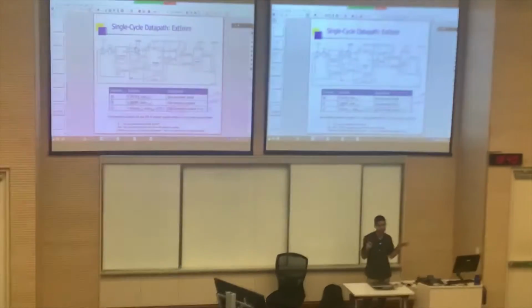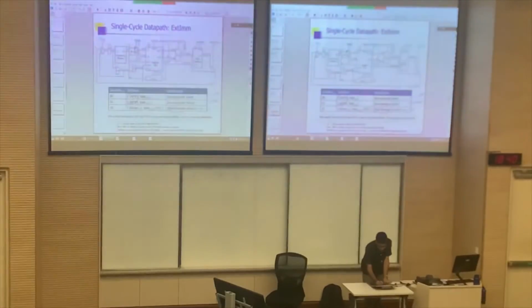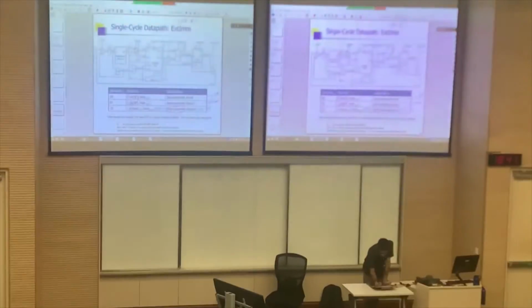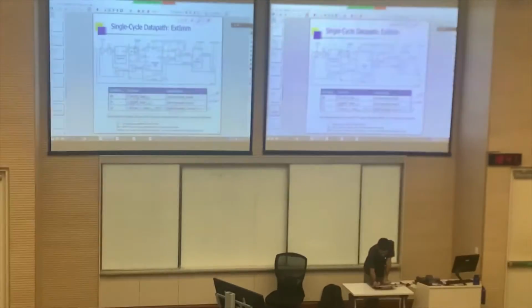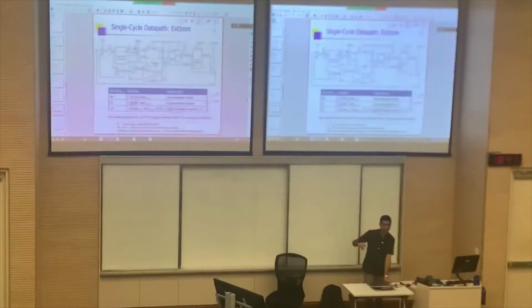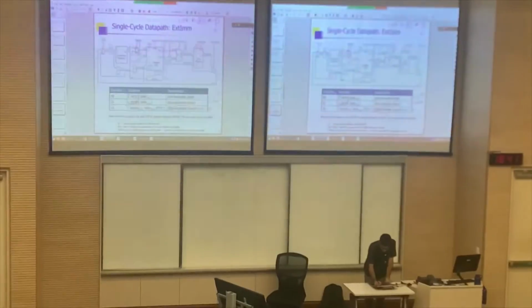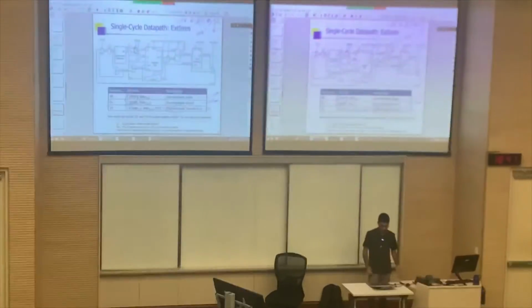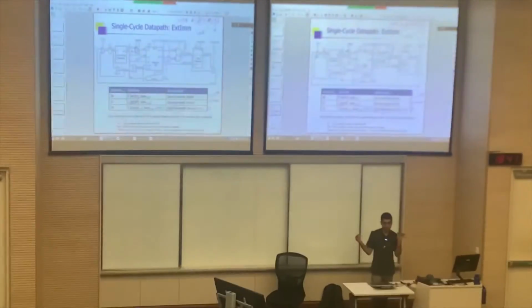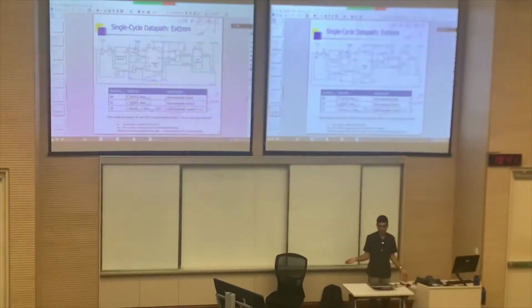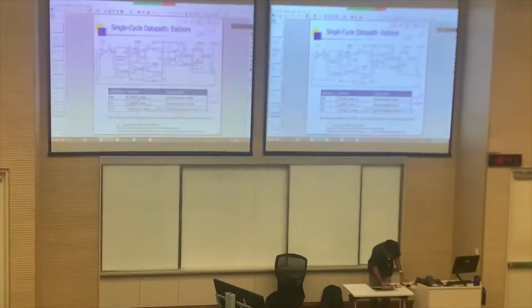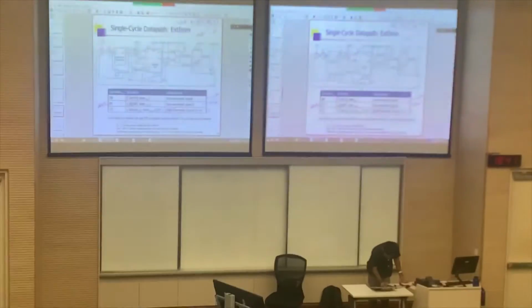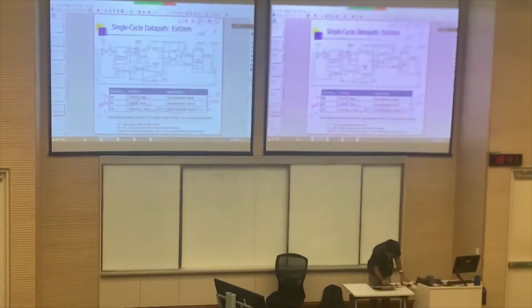For the other two, the immediate itself is unsigned. But for memory instructions, there is a notion of sign that comes in through U bit. So it's entirely possible to write something like, say, LDR R1, R2, minus 4. This is entirely legal, where 4 will be encoded as the immediate, and this will cause U bit to be 0. So it's sort of a sign and magnitude system where the sign comes from U. This is signed, and this actually is unsigned.